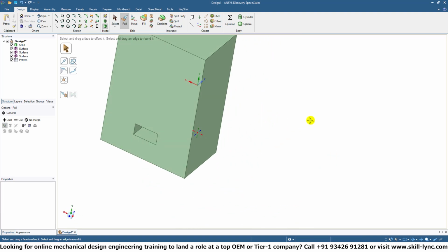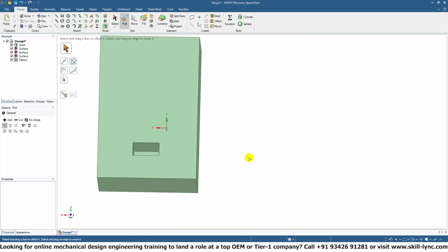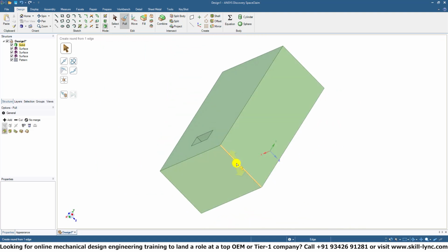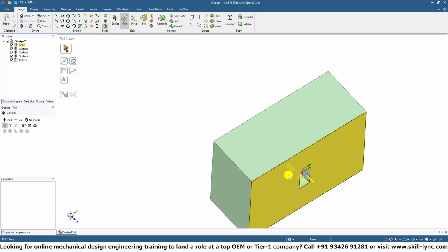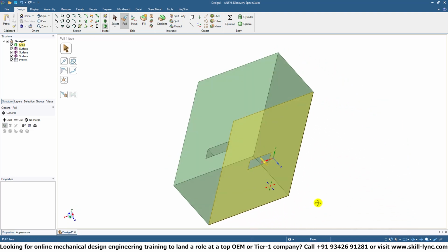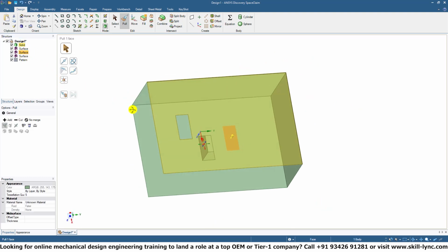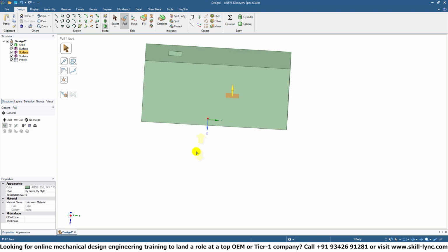So from a geometric or engineering perspective, what this allows you to do is set a center surface from which all of these cuts or extrudes start. And you don't have to cut, you can create a boss or an extrude.